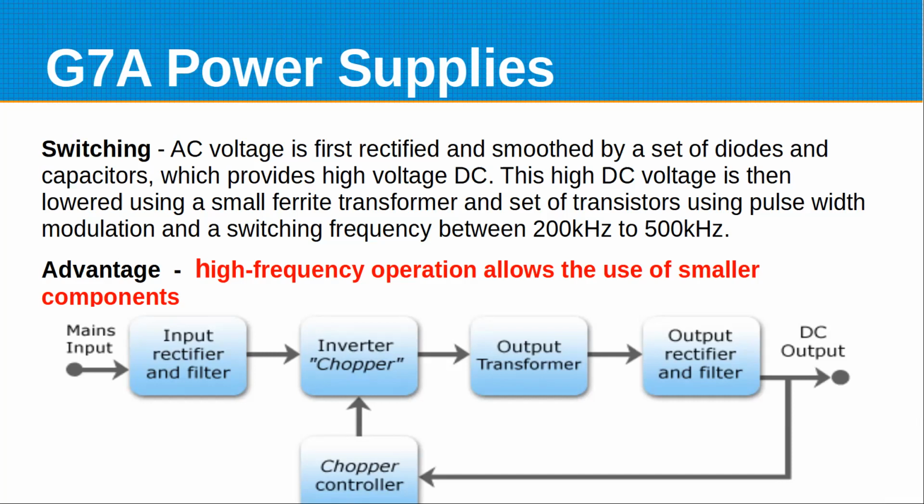It converts it to pulses whose width is proportional to the amount of voltage that you want out, because you're going to take the area under the curve, basically smoothing those pulses. So if you wanted the full output, you're going to have almost 100% duty cycle.